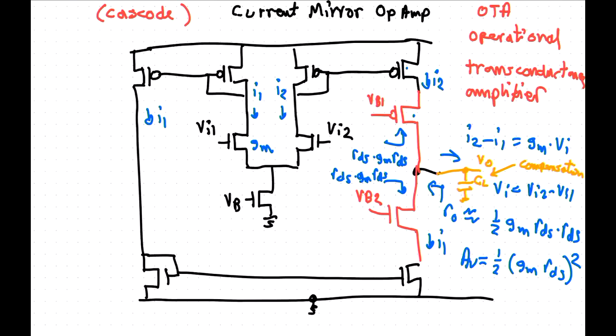If you have two gain stages, you probably do need to do a Miller computation. But for an OTA stage, it's fine. This one can be considered a two-stage OTA, but I consider it one stage because there's only one point in the circuit where the gain happens, and that's at the output node. All the other structures are riding around the current at low impedance levels.